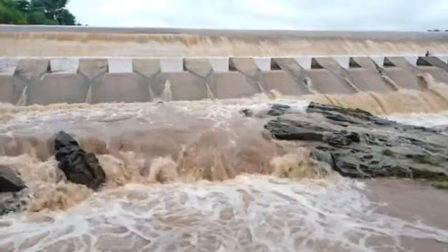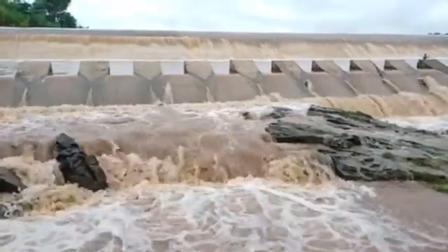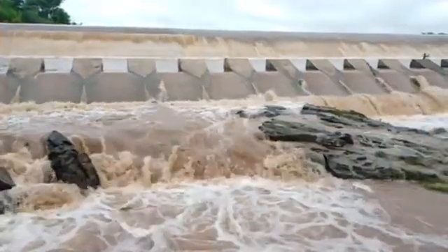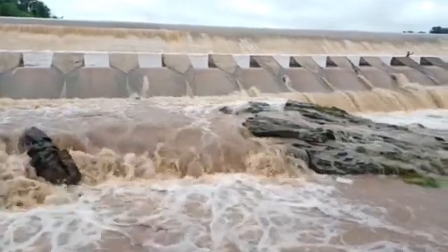Now, I will talk about the types of contaminants that are filtered out by both rapid and slow sand filters. For rapid sand filters, it is effective to remove coagulated and flocculated solid particles and impurity sediment in the wastewater during pre-treatment. On top of that, rapid sand filters can also remove turbidity of the wastewater.